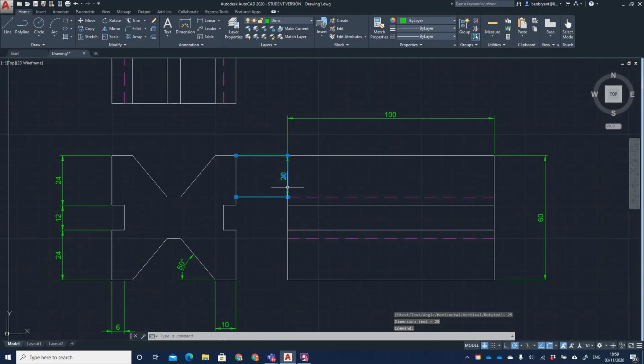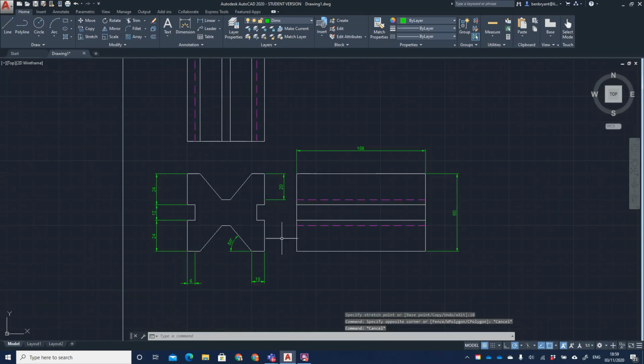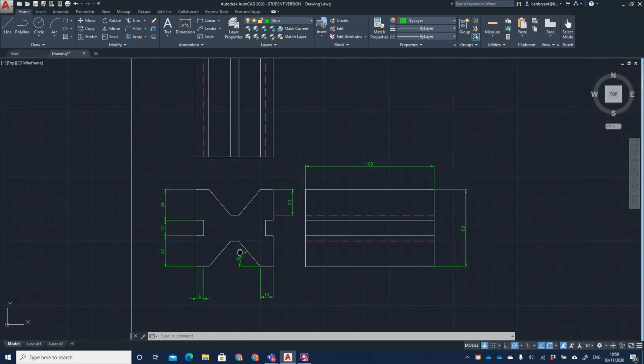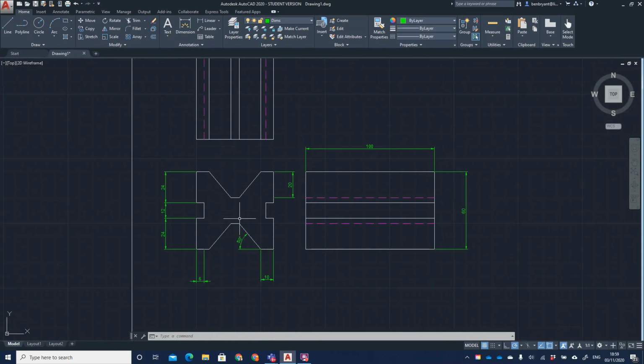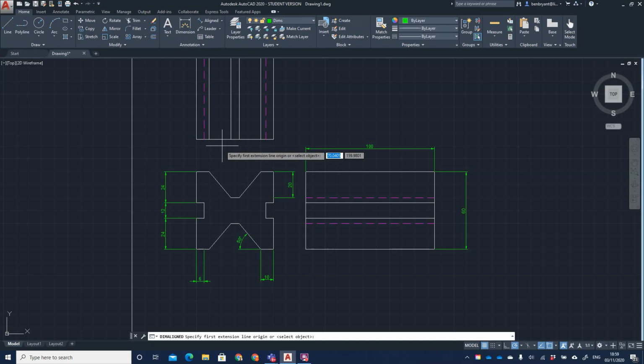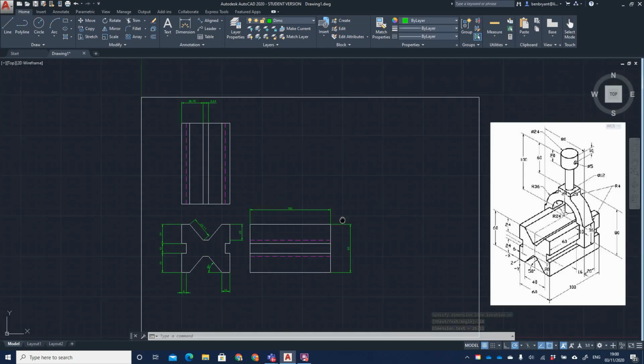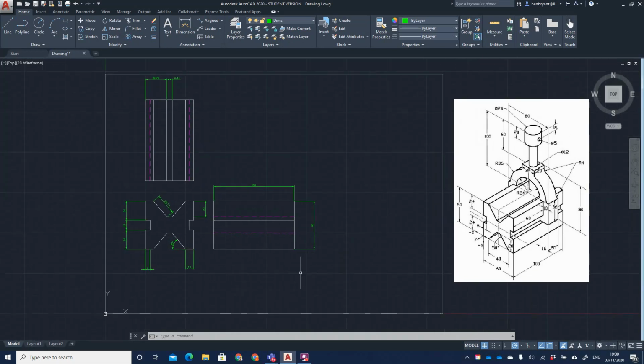So again, having a 20mm offset on that one is quite close to my next part, so I'm going to change that one to 10, like so. So then my V is 20mm deep, it's 6.344 wide, it's then 26 from the left-hand datum, and then my angle is 50. Sometimes some people might want to put in the angular length as well. It just gets quite messy, so you have to be really careful on how far you're displaying away. But if I put another 10mm, it should be quite nicely sized as well. Those are all the functions that I need to give to a competent machinist to then make my part.